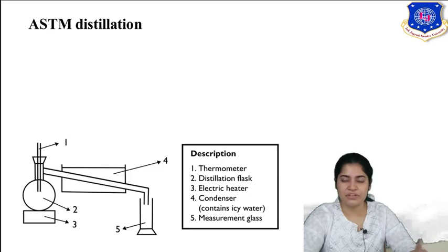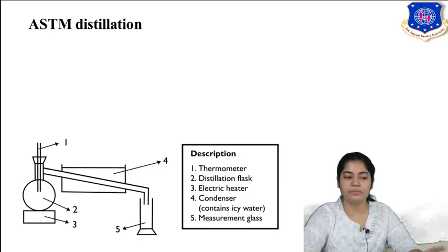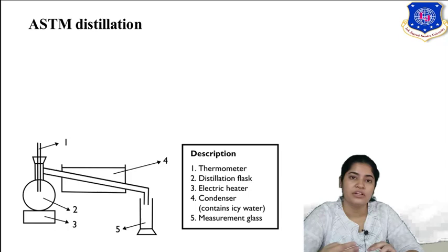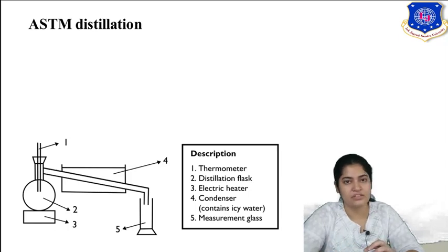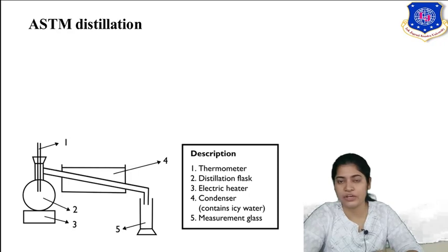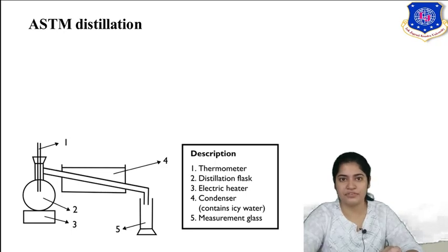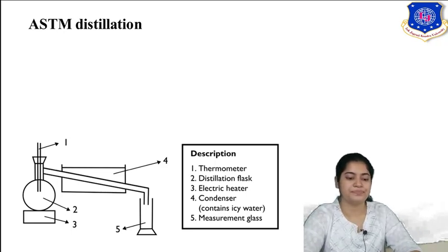The difference between TVP and ASTM is that now you are not providing a fractionating tower. You are not providing packing material. So there is less contact between vapor and liquid, plus you are not providing a reflux condition. Well, actually what is reflux? As a revision of your distillation, the more volatile component which vaporizes travels, is condensed and liquefied. And reflux is when you take a part of that distilled liquid and transfer it back into the fractionating column. So that is reflux. Now here no reflux is there.